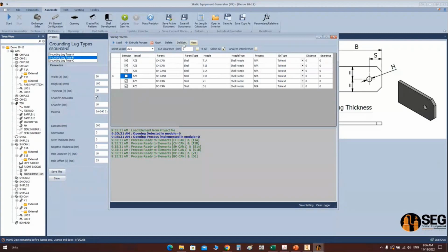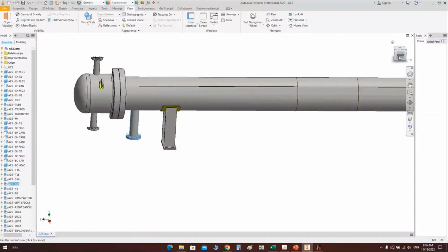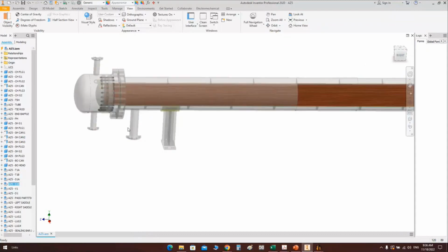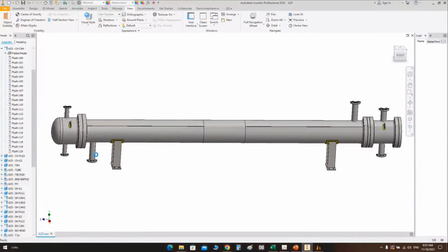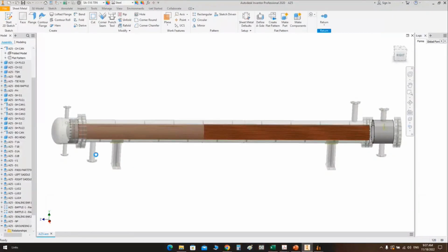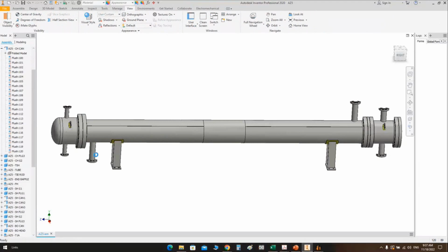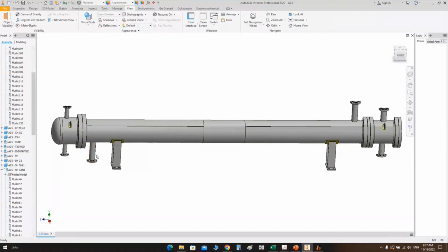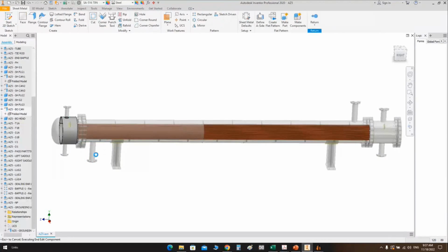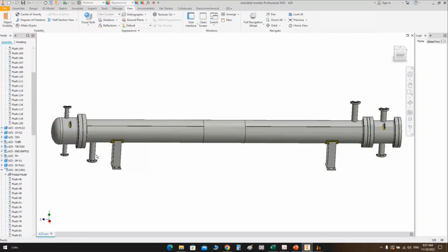Here we can make a cut with a cut clearance of 2 millimeters, and let's extrude cut to create a cut for those nozzles, except nozzle S1B. We will generate the hole of this nozzle separately with the same tool but with another option, analyze interference, because this option gives you the ability to detect the real item on which this nozzle is located.